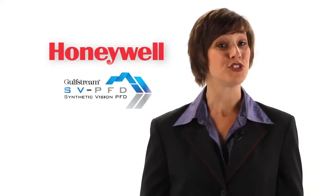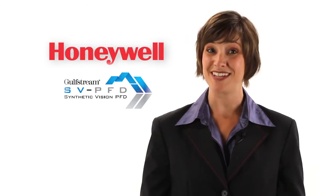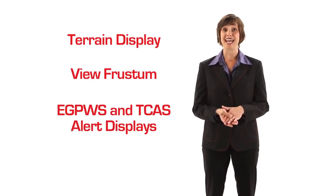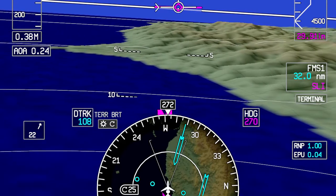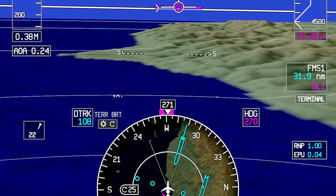In addition to the features already discussed, SVS 2.0 features an enhanced HSI. The enhanced HSI features terrain display, a view frustum, EGPWS and TCAS alert displays, as well as the standard HSI information. The enhanced HSI presents a top-down view of terrain similar to that shown on the map display.